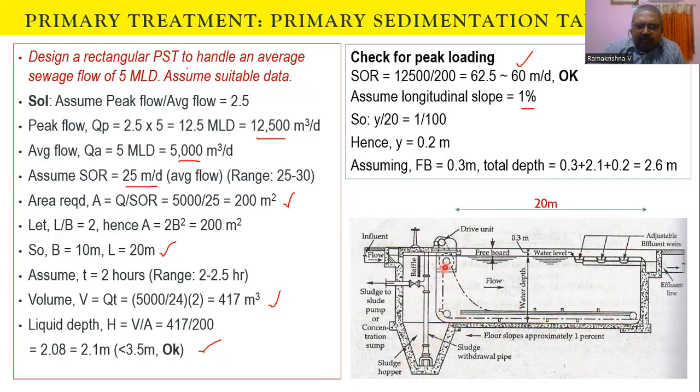This belt will be run through a driver here, and all the treated water after settling will come out through the overflow weir. This is a weir here. This will enter into the outlet channel, and from there it goes out. And here we are providing a number of weirs along the width of the tank so that the water flowing across the outflow weir can be adjusted.